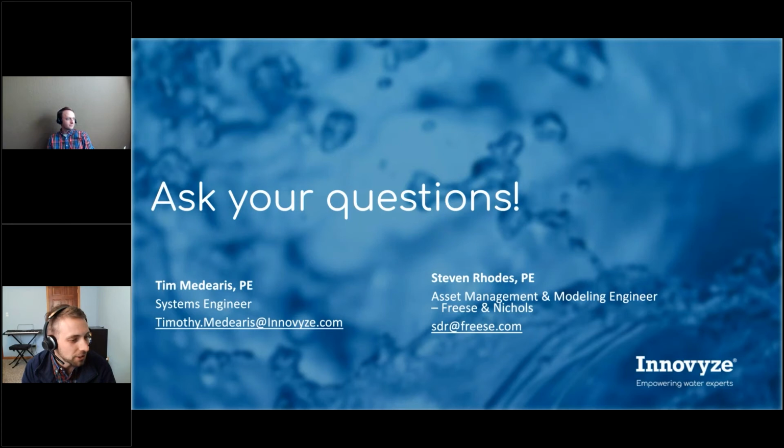Perfect. I had a question about wastewater treatment plant modeling. Were you able to connect this to the overall collection system model as well? Yeah. So in that one example of the grit removal, we actually did that. We connected the treatment plant model to the collection system just to get that direct connection and make sure there was no misunderstanding of what that downstream HGL was for the collection system.